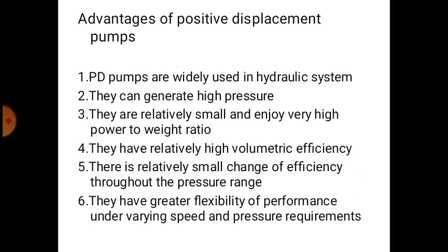Advantages of positive displacement pumps. Positive displacement pumps are widely used in hydraulic systems. They can generate high pressure. So positive displacement pumps generate very high pressure. In that too, if you use piston pumps, they will create more pressure than the vane pumps and gear pumps.